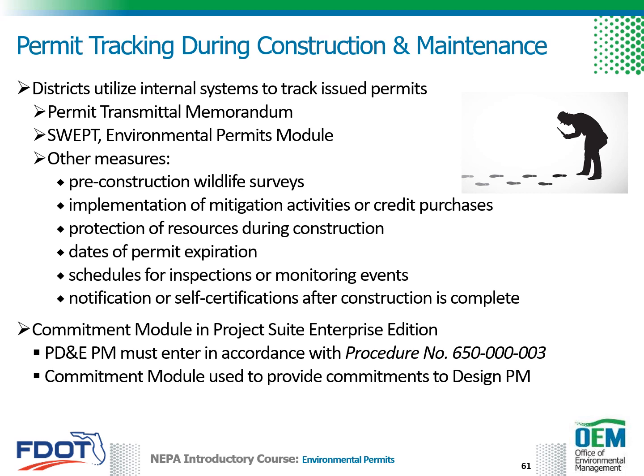FDOT staff also implement measures to track the completion of tasks associated with each permit, such as pre-construction wildlife surveys, the implementation of mitigation activities or credit purchases, the protection of resources during construction, the dates of permit expiration, schedules for inspections or monitoring events, and notification or self-certifications after construction is complete. Spreadsheets and/or databases may be helpful, especially when the tracking tools automatically notify the user of upcoming dates and scheduled events.